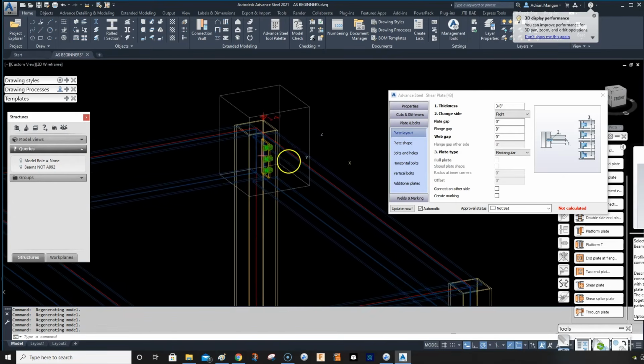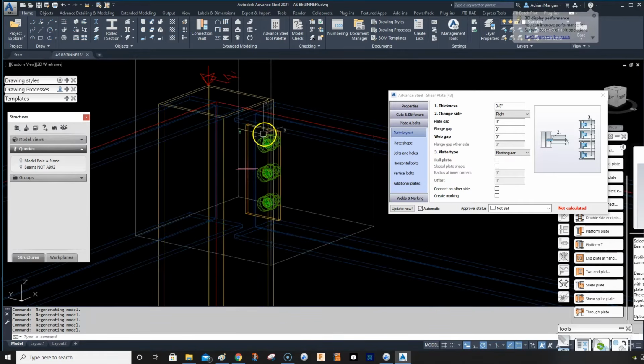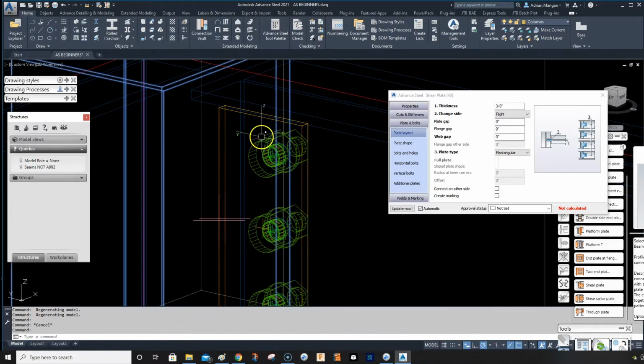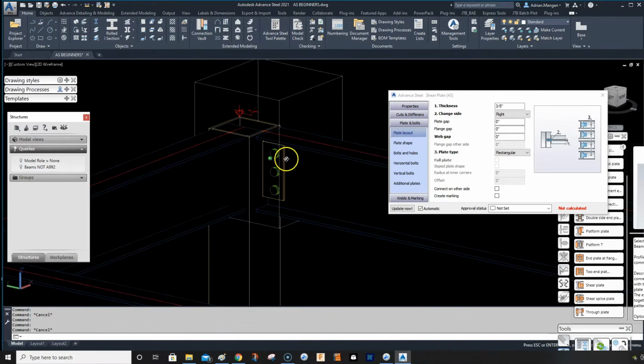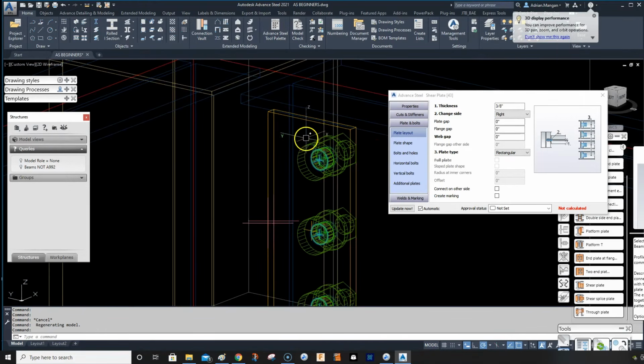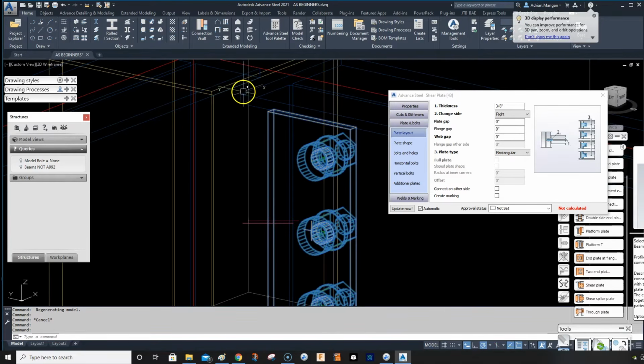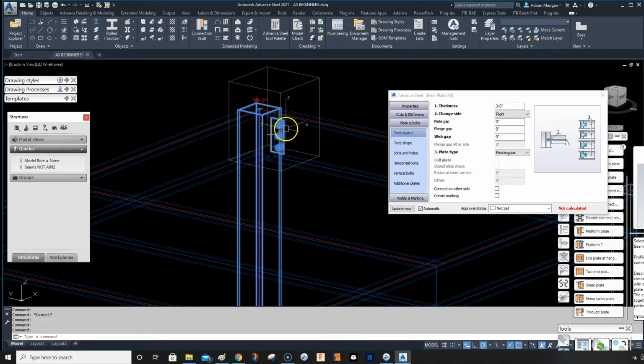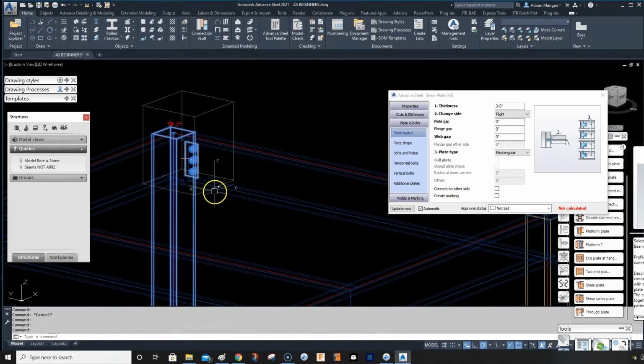So this can be a problem because the bolts are associated with the steel where the head of the bolt is. Right now the head of the bolt is on the side of the plate, so these bolts will be on the material, on the bolt list on the column. But we don't want them on the bolt list with the column, because if they just want one column or all the columns first, the bolts will go with the columns and you don't need them, and then they're going to get rusty and they're going to be on the job.